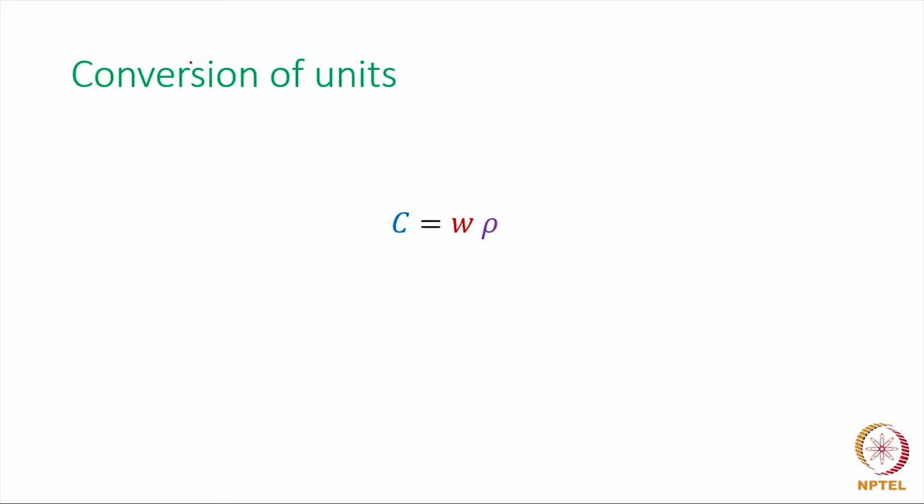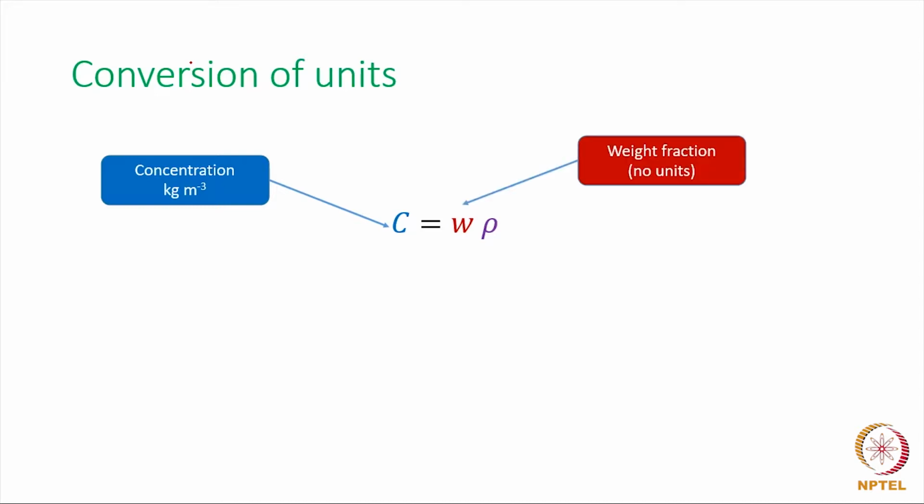Wilkinson. We have all the conversions that are neatly described there. So you have the concentration of the species that is diffusing, let us say hydrogen in solid nickel, and you would write that as the kgs of hydrogen per meter cube of the solid nickel, and that has to be then expressed in terms of the weight fraction into the density, and the weight fraction can also be converted from weight percentage by dividing by 100, and the density we mean by the density of nickel, because that's a matrix in which the